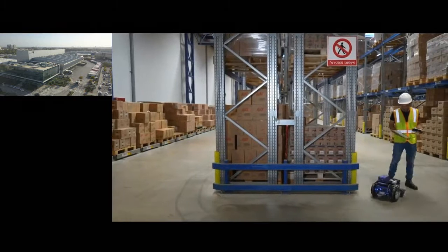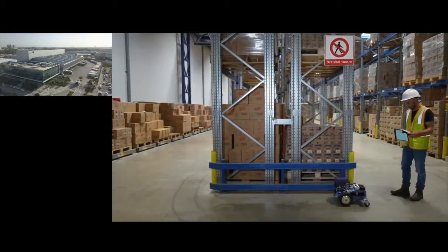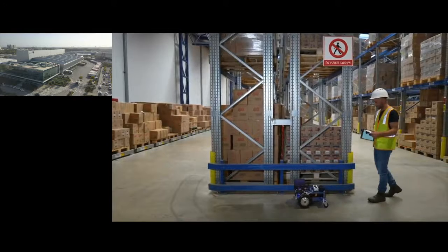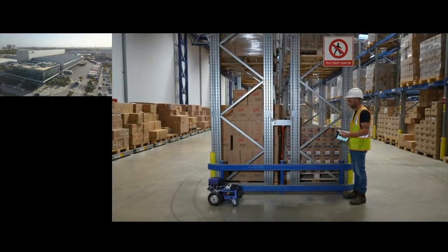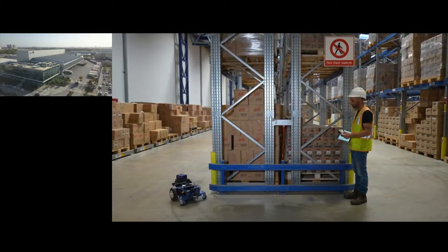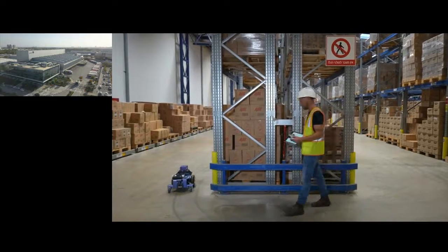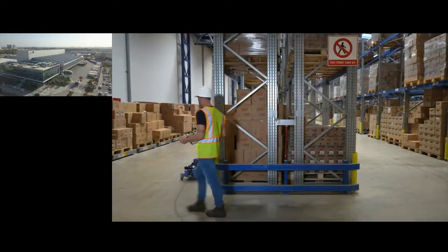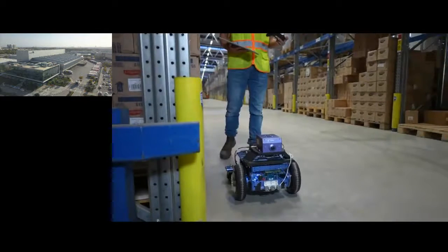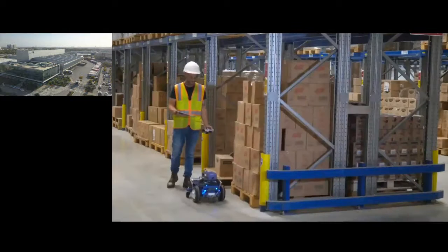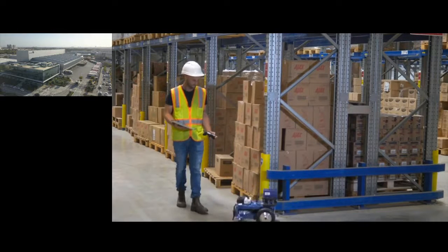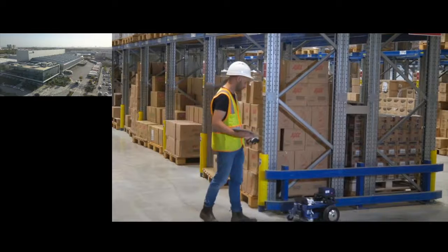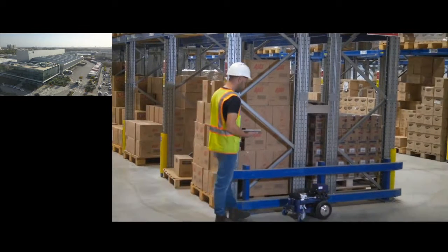You can see there are a lot of people still working in the warehouse. You don't need to stop the operation, as I mentioned. And you can see the robot will travel back and forth in the aisle. It will usually try to close a loop, as a traditional SLAM system needs, to get a more accurate and dense graph. And that's about it. After the perception engine closes the loop, it will be ready to use within a minute. So that was site learning.